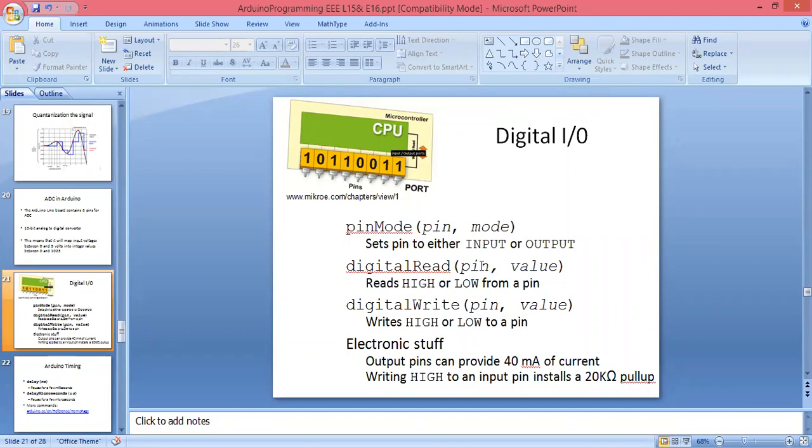And if you are not giving it, and you are connecting that LED to the ground terminal, it means that if you are not giving any input voltage, if you are giving low value or zero value, we can use digitalWrite in brackets D13 comma LOW. So what will happen to the LED at D13? That LED will stop blinking. That LED does not blink. And if you are receiving any data, at that time we are using digitalRead. And if you are transferring data, we can transfer data by using digitalWrite.